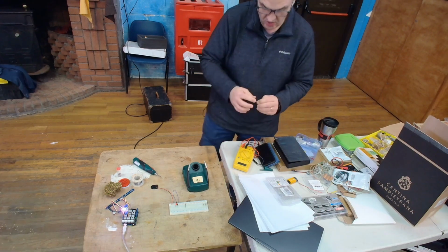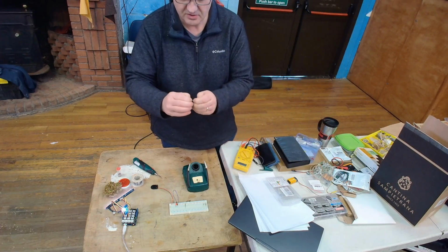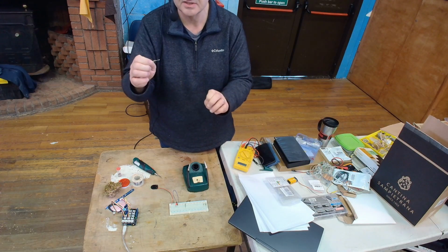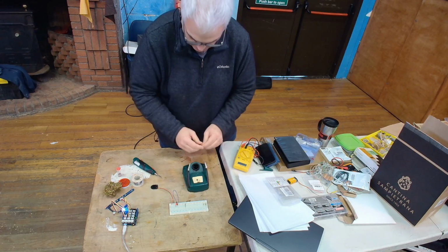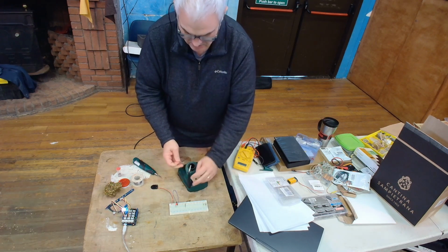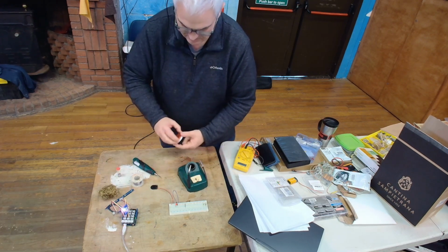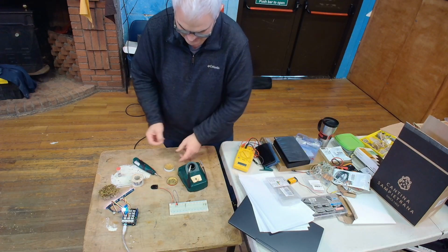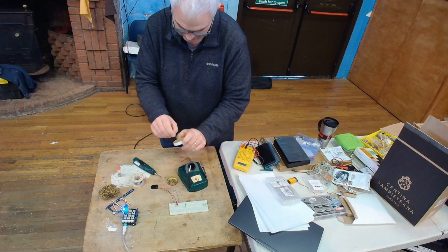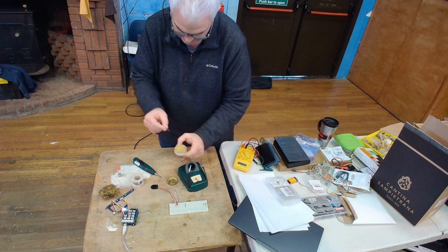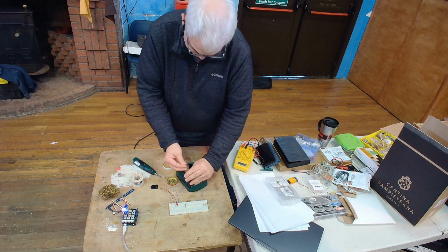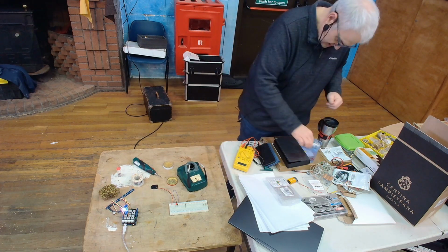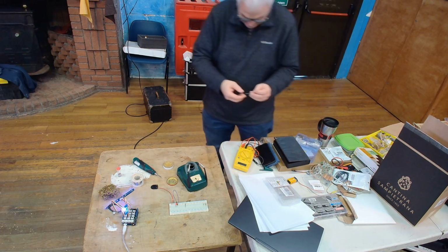I'm just going to wire one of these resistors. The other thing, the LED, it matters which way you wire it. The resistor, it doesn't. It can go either way. Doesn't matter. So if you're soldering something, this is soldering paste or flux, which just cleans up the connection. And the same if I want to solder that to the LED.